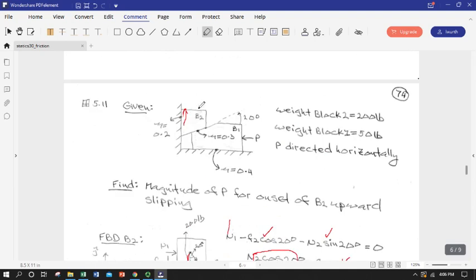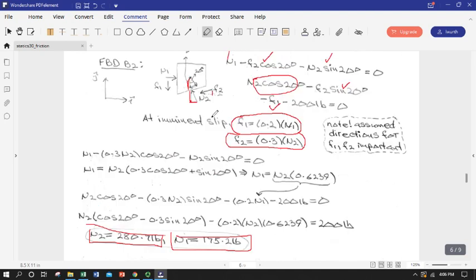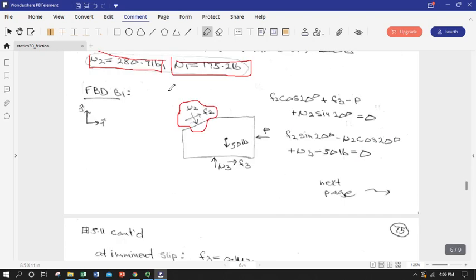So basically, if we go up to our other diagram, as we push block B1 to the left, B2 is effectively sliding to the right relative to B1, a little bit of relative reference frames. And so effectively B1 would be moving horizontally from the standpoint of this plane, even though it's probably not going to. So F2 was drawn to the left for the same reason that F1 was drawn downwards. So of course we do equal and opposite when we go down to our block 1 FBD.